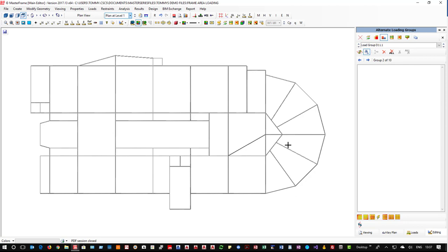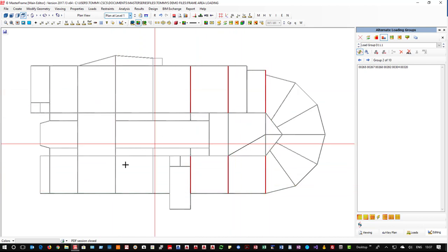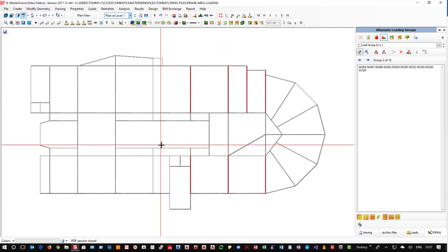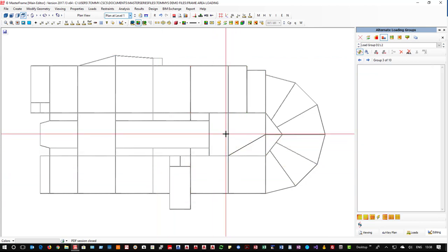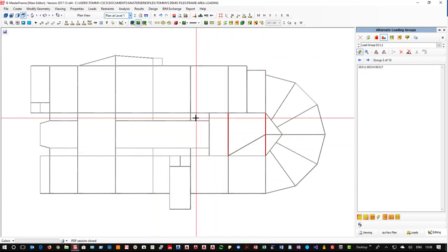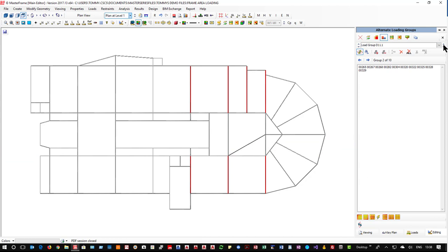But if we wanted to do pattern loading on this, so we had a maximum, minimum, maximum, we would need to turn around and say, in apply mode, that's a D1, that's a D1, and you could then do that, and that is D1, and you could do that as D1, and that is D1, and maybe even that as well, do no harm. And then you'd say your D2s are in fact the counter members, those, and in this case those. So you'll see now that your loads are separated.